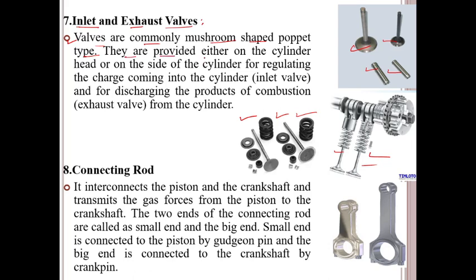They are provided either on the cylinder head or on the side of the cylinder, for regulating the charge coming into the cylinder through the inlet valve, and for discharging the products of combustion from the cylinder through the exhaust valve. This is our cylinder. From the inlet valve the charge enters, and from the exhaust valve, after combustion, the gas comes out. This is a simple concept.